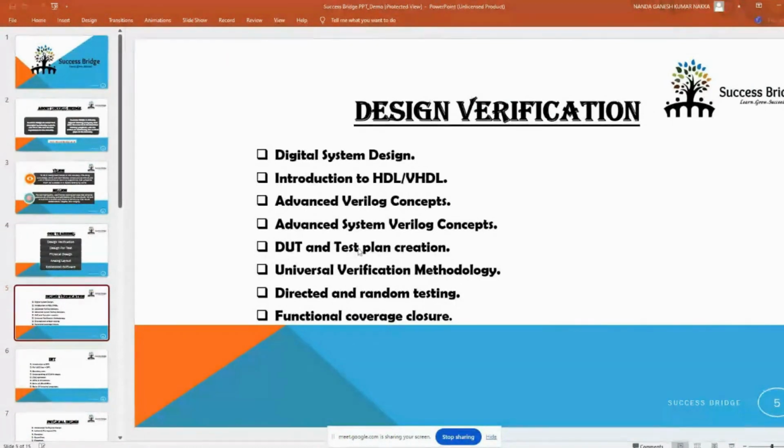Okay, so he is responsible for the functional coverage also. That means, of the total number of combinational logic gates or sequential elements that you have in the design, how many of these logic gates you are able to test. That means you are able to 100% confirm that I'm able to give the input to the gate, and I'm able to get the expected output as per the truth tables of these logic gate elements. Okay, so this is the responsibility of a design verification engineer. Okay, this is clear. I'm going to DFT next.